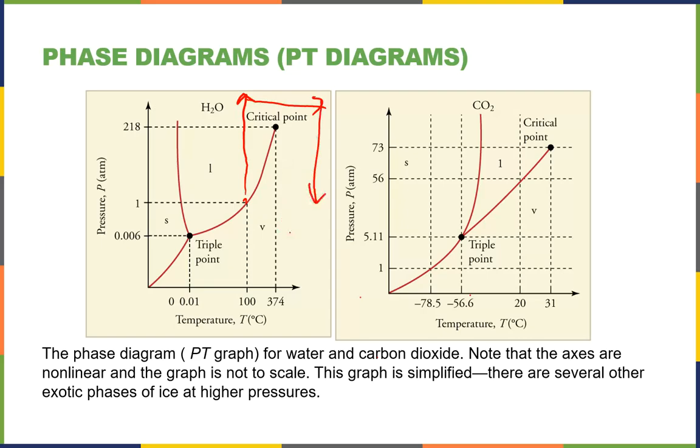Then lower the pressure, keeping the temperature constant. Then lower the temperature, leaving the pressure constant. In that process, notice what we did not pass: the red line that's separating liquid, L stands for liquid, from vapor, V stands for vapor.